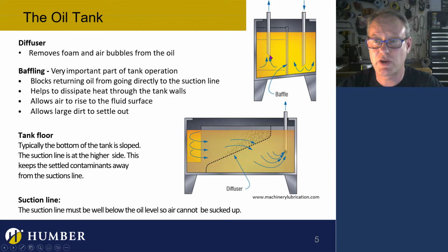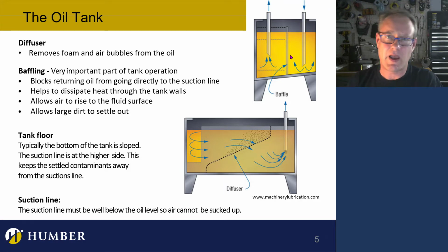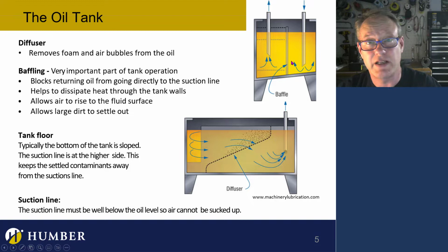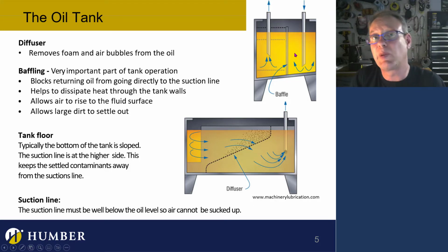This baffle is going to keep separate the material that's going in and the liquid that's going to be sucked out. Essentially, the baffle in between allows any particulates to come down here, settle in the tank, and then the clean fluid gets sucked up here. The interesting part of this picture is that this return line is close to the bottom of the tank. It doesn't really matter where it is, although it has to be below the fluid, and I'll talk about that in a minute.